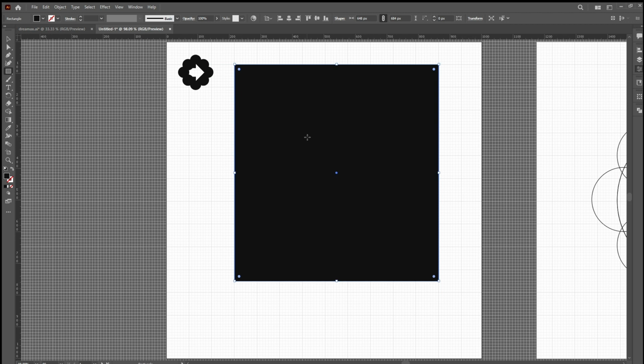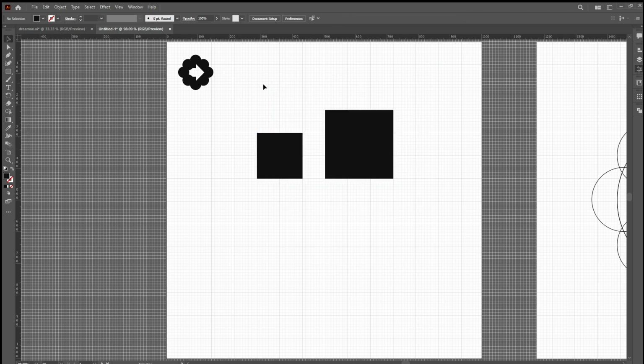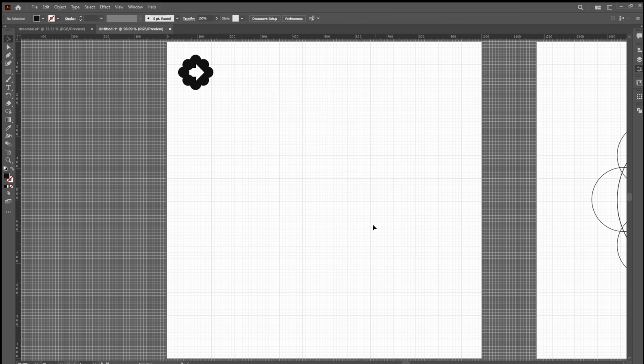All right, so that is how we use the grid, and ensuring that snap to grid is there is very important. So if you miss that, you can just take this video backwards and see how I did it. Or let's do that again. I'll click on view at the top, scroll down to snap to grid, and it's going to snap to grid. Mine is turned on, that means it's actually on at the moment.